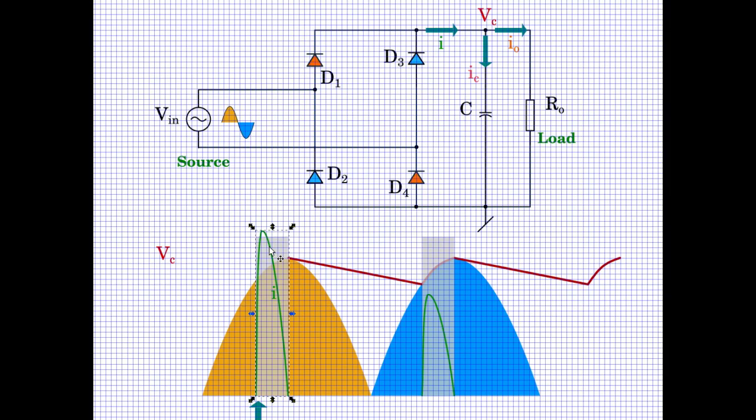But keep this in mind that all is not rosy and all is not well and good with the circuit that we have just discussed. The turn on current surges can be pretty high, and it could be a big drain even on the wall socket outlet. They have to be rated for such high currents. Therefore, we would like to put a series impedance somewhere here and limit the current surge.